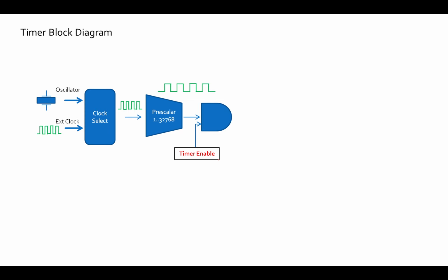I have to enable the timer. Timers are not what's called free running. They need to be told to be enabled. Once they're enabled, they then start counting. And let's assume I've set the counter in that red box in there to 100. Well, it will get a signal from the oscillator, it will go through the prescaler, and it will go from a high to a low, and then we'll increment it, and it will go 101, 102, 103, 104. It will carry on going through there until it gets to, we'll say, arbitrary number 254, 255.